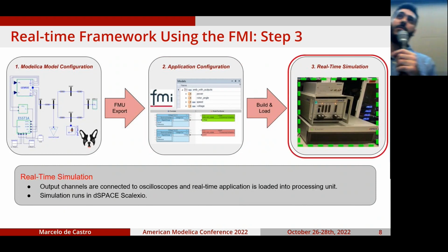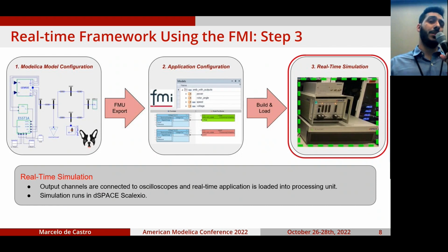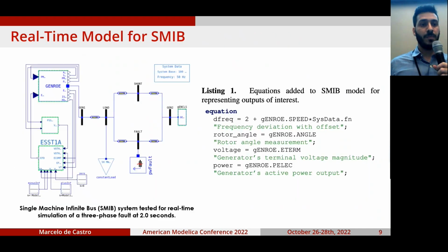And then the last step is just to use the build real-time application from ConfigurationDesk to the real-time simulation. In this case, we use dSPACE Scalexio, and all is done using the FMU natively. So we don't use any additional toolbox or additional path or anything like that.